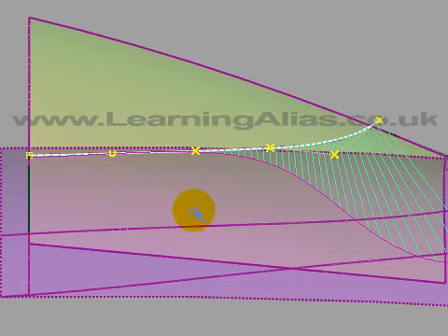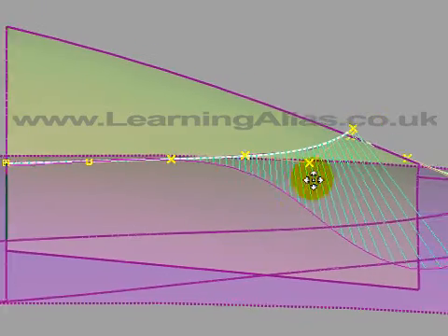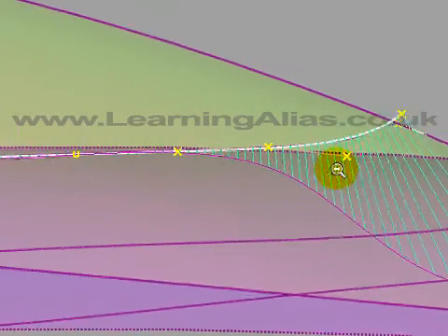This is my next step. I stress that this is the way I do it. It's not necessarily the way that other modelers do it. I do it like this and it works. Take a degree 5 curve and shape it to meet the end of this curve here. So, you see that it kind of passes through the end of that curve. In fact, we can adjust it just a little bit maybe.